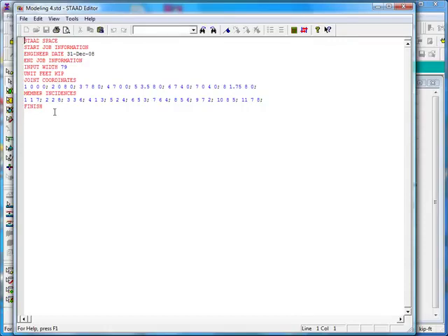The Staad editor uses certain color conventions to identify Staad.Pro keywords, numeric data, comments, and so on. The color convention is that it uses red to identify text that it recognizes as a command. It uses a black font for items that it refers to as user-defined text or labels or names, like the date that you see here. The color blue is used to indicate anything that Staad interprets as numerical values or data.